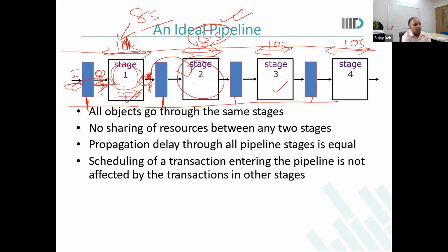So in our common language, we call it the critical path. The critical path is the path which is taking the most amount of time, and that determines at what clock frequency you can operate this. This is nothing but your register transfer logic circuit. Now, if you want to make it faster, then you have to look deeply into this critical path and see whether I can improve this delay further. If I can improve it further, then I can clock it better.